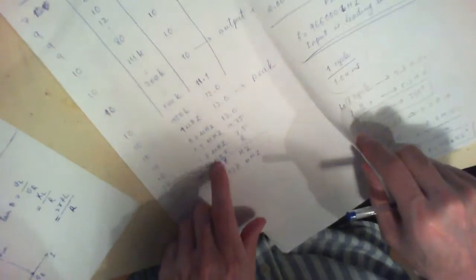That was the peak of this voltage, meaning that if you plot the output voltage versus the frequency all the way up to 1 megahertz, then the voltage was at peak, and then it started falling down. For example, at 1.5 megahertz it was at 9.75, at 1.8 megahertz it was at 7.5 volts, at 2 megahertz it was at 6 volts, basically 60% of the input voltage. This was all the way up to 2 megahertz.